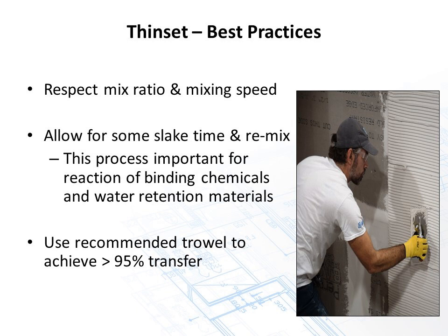That's important. If you're in the freeze-thaw climates again, I remember in Colorado I went to a bank one time where unfortunately there was marble set in a panelization system by a drywall shop, and coverage was probably about 20%. They had to put scaffolding up over the front door and the back door of the bank just so people could get in and out without having to risk their lives.